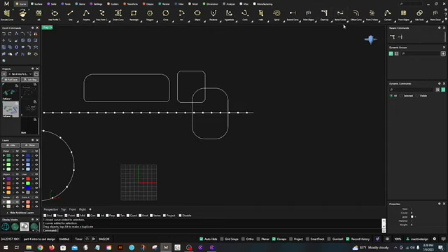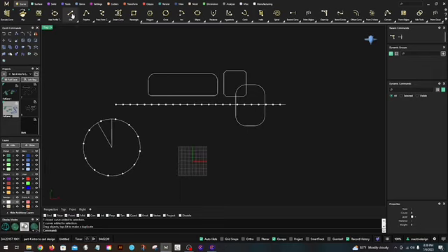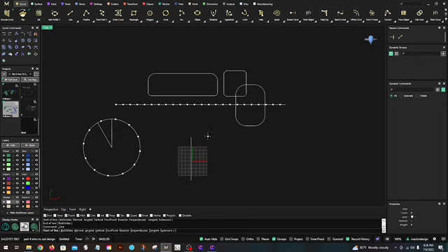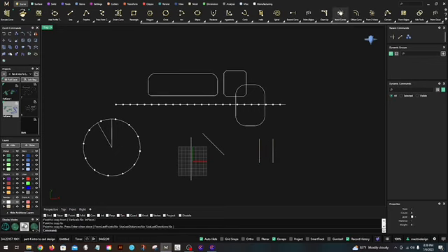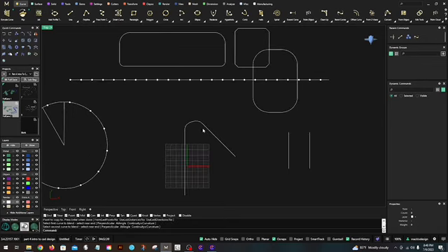All right, let's see what else is up here. Blend curves. I know this one. I'm going to bring in a curve here and here. And then we'll do a straight one. I'm bringing in a straight curve and duplicating it. Blend curve. All right. I selected the top blend curve. It said select first curve to blend near the end. There we go. And then you want to do the second curve near the end. There it is. Very nice.